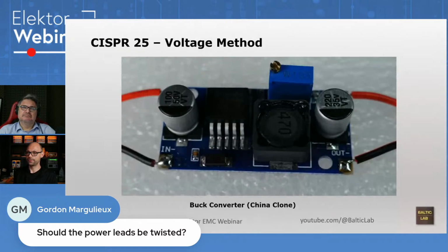When we talk about deviating from the standard test setup, you can do anything that will happen later on in the vehicle installation. Whether or not this will make a difference in this particular case is highly questionable, because there's almost no common mode noise. I'll spoiler that much. But yes, it can make a difference, and you are allowed to do it. As a matter of fact, you must do it if the device dictates it in its manual.